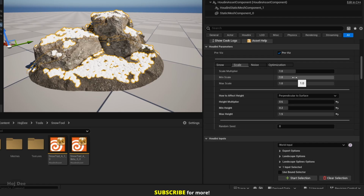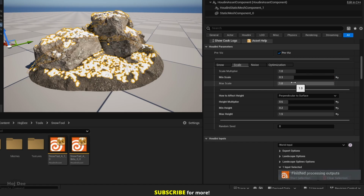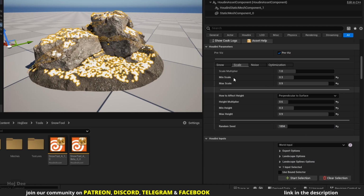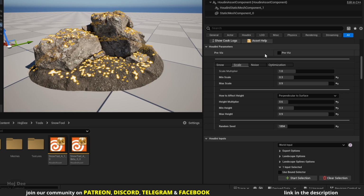Let's set the min scale to 0.3, max scale to 0.9, and do the same for the min and max height. Now if we change the random seed value, we can have different results. Let's disable the previous option to see how the snow mesh looks. If at any point you want more or less snow, just enable the previous option and tweak the parameters again.